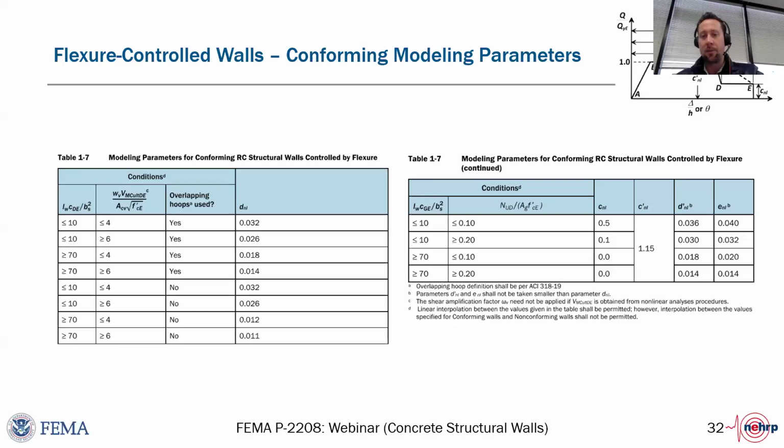It's really the lambda in combination with axial load. And that's what determines both your ultimate deformation capacity, so when you actually lose total load carrying capacity of the wall, and also your residual strength. That makes sense because usually that means that you're crushing the wall. So axial load does tend to influence that crushing and whether you truly lose all that concrete along the length.